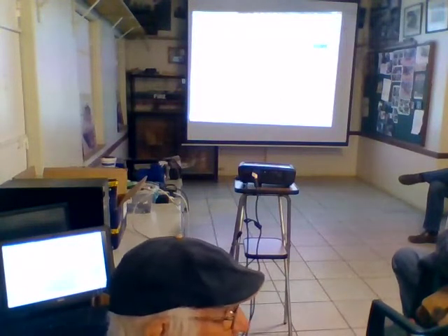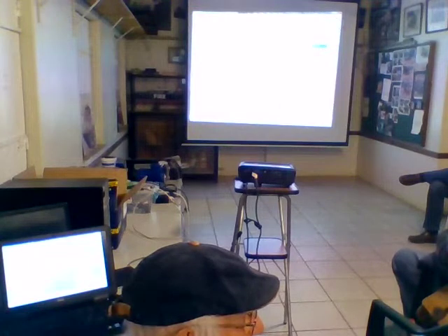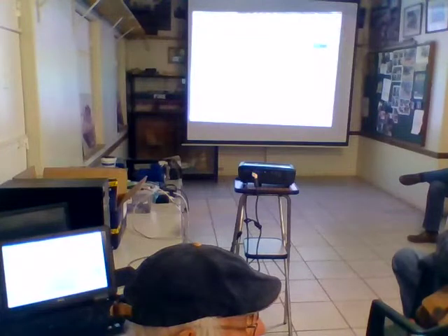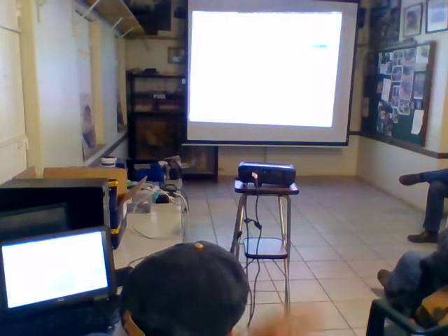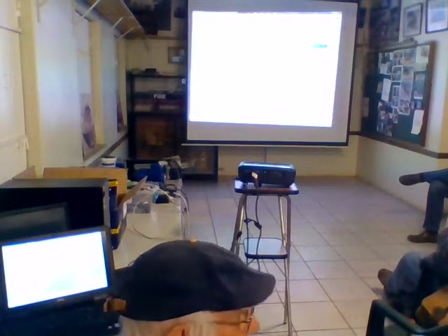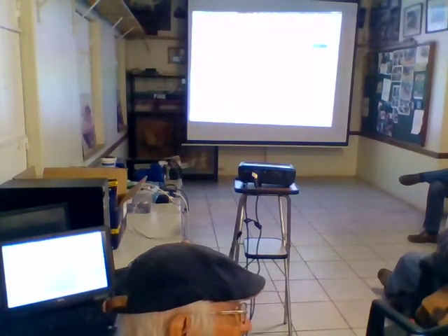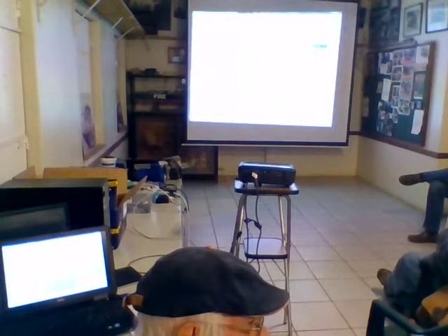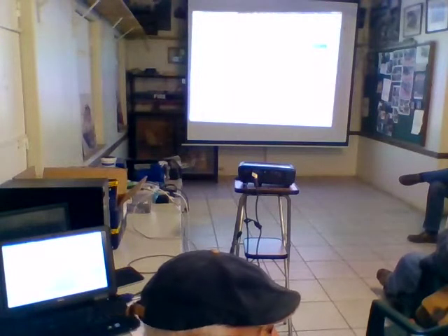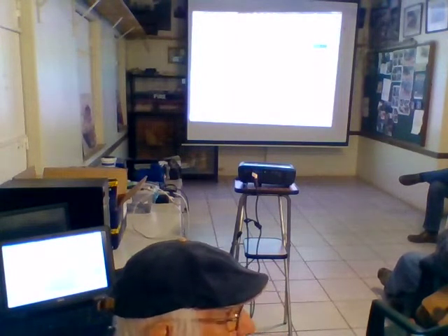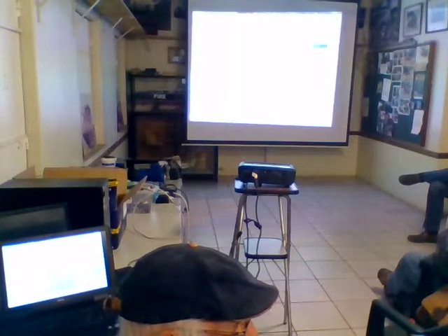But the deflection values, what I've seen here, says that the principle of the design is very good. Yeah, now I'm happy with it. I've checked it. This is a very preliminary model that I'm making now, just a first model. But I've checked it, and it's getting sort of 6 to 10 micron for 100 Newton. Now, you don't need to use 100 Newton. That's a big cut. A finishing cut is like 10 Newton or 20 Newton. So to get a better accuracy, you go for smaller cuts, a finishing cut.